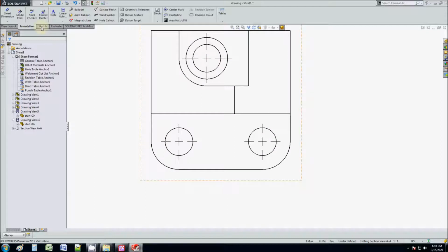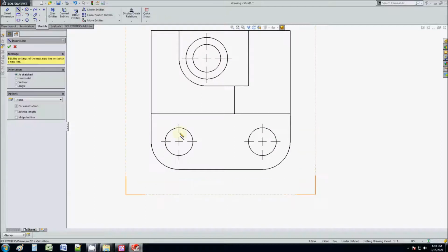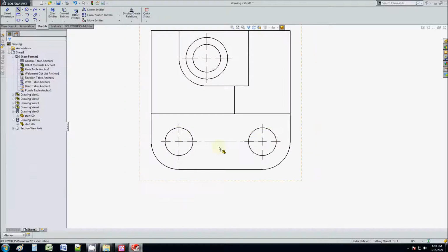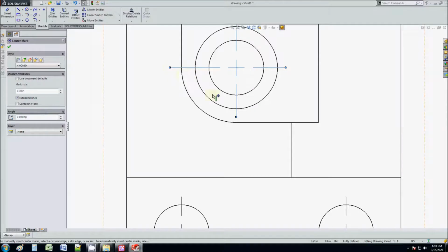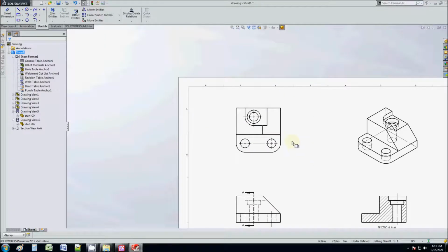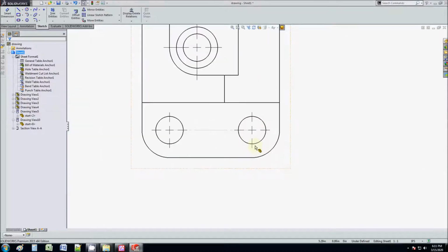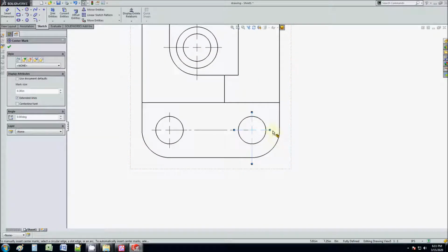This one is not really symmetrical about the whole model. So let me show you another way you can create a center line. Okay, it's just this one. This one is like custom. You can make it go anywhere you want. So remember, center lines are supposed to connect together. So this is why I connected the 2 just like that. Also, you'll notice that this is concentric. This fillet is concentric about the center. So what I'm going to do is extend this out because this is still sharing the same center as that. Same with this. See that fillet is sharing the same center.